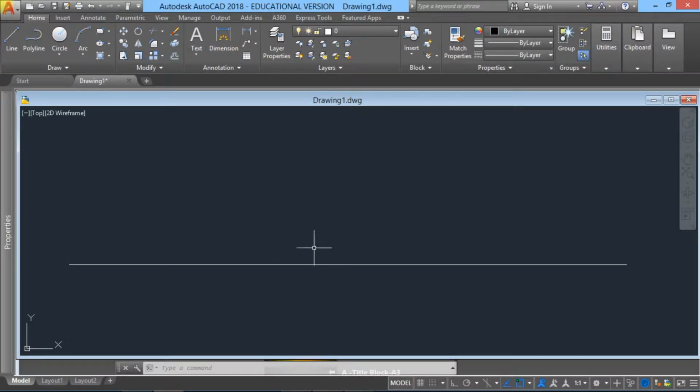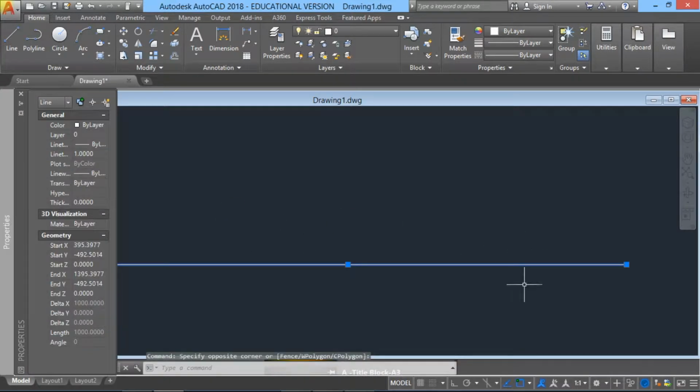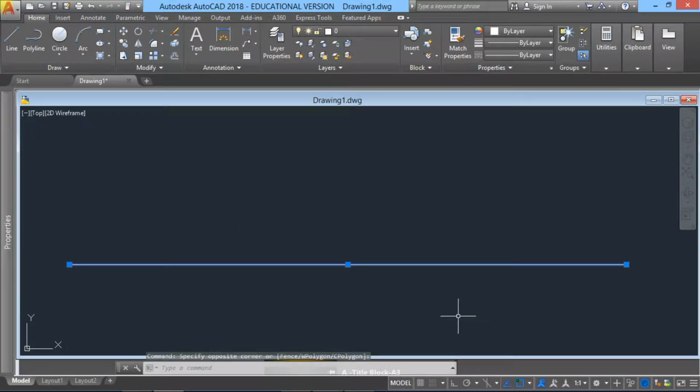But when you add the second line to this line, you will have a distance between these two lines. That distance in each scale can define one kind of material. In this case, our external wall is gonna be brick veneer. The width for the brick veneer is 110.